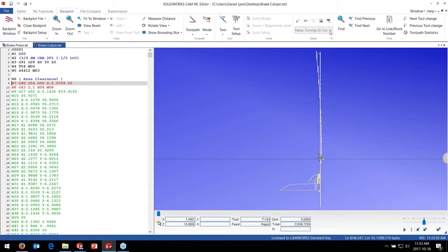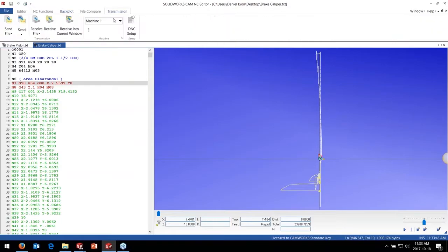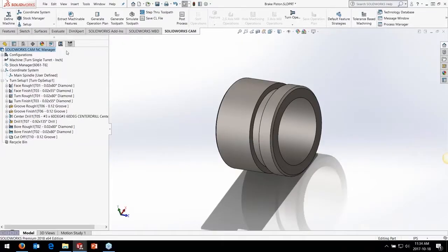So if we're using a horizontal mill, or maybe a 4th axis rotary on our vertical mill, rotating parts around, SOLIDWORKS CAM will actually support the indexing or pre-positioning, or 3+2 as people call it, for 4th and 5th axis rotations in the professional version. The other thing is it's a SOLIDWORKS assembly.